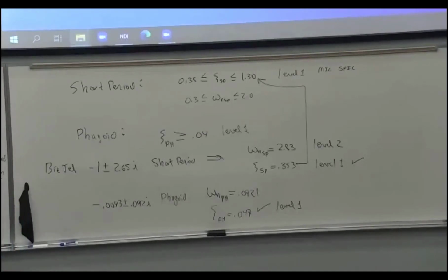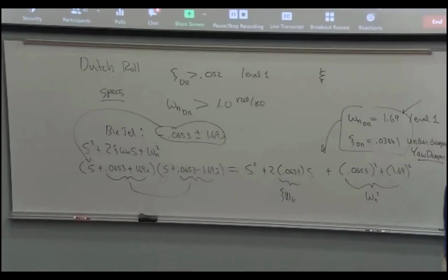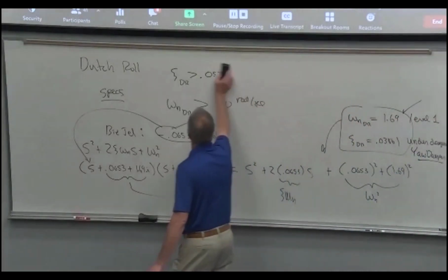So the idea is, where do you get a lot of the parameters that show up in the aerodynamic models? We've talked through in this class how you would calculate them using the charts for the airfoils for the wing, and then we build up the wing and we get like CL alpha, the lift curve slope for the wing, all of that. But once you've done the calculations, then you want experimental validation of the aerodynamic numbers. These are the numbers that go into those Z_u's and X_delta_E's and all those parameters that show up in the dynamics.